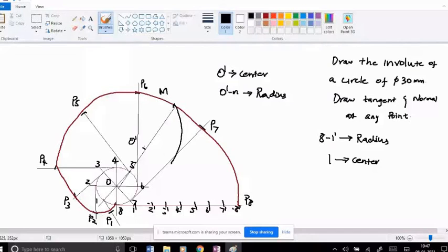Okay, you need to make a half circle like this. This half circle will cut somewhere on your generating circle. You look at this one, it cuts somewhere on your generating circle. If you look at this, you can find a similarity: your chosen point is between P6 and P7, and the arc cuts between 6 and 7. That means your bisecting is proper.